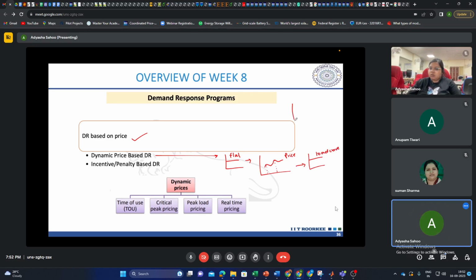because when we are having this type of load curves with peaks, it will lead to inefficient utilization of the resources. The utilization factor here will be very less, because to meet this peak demand we have to assign some resources for a very small amount of time, and for the rest of the time they will be idle, so their utilization factor will be very less.